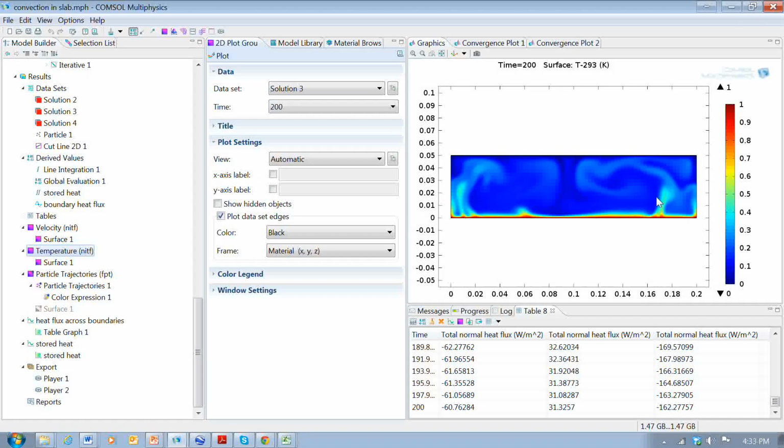And so essentially what happens is the solid part of the insulation doesn't really conduct heat very well, but it's the air that's really doing the insulating. What the solid part does is prevent the air from convecting and transferring heat by convection.